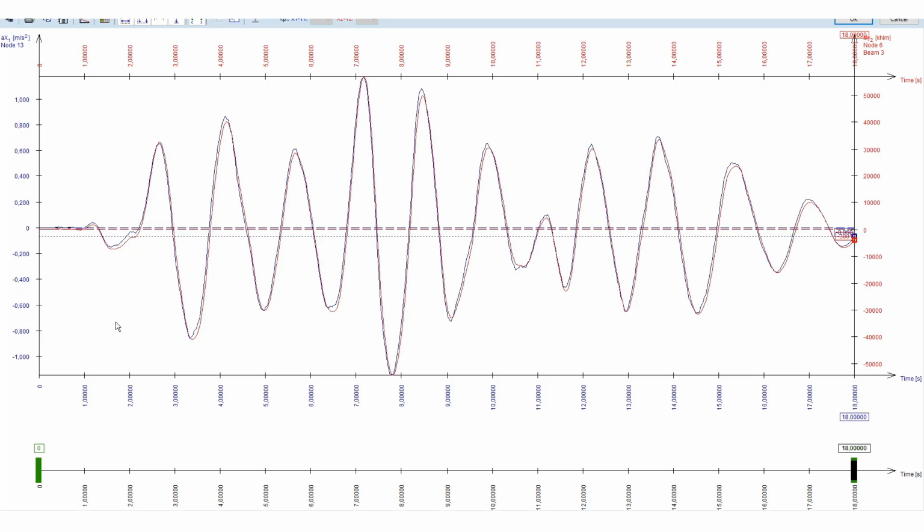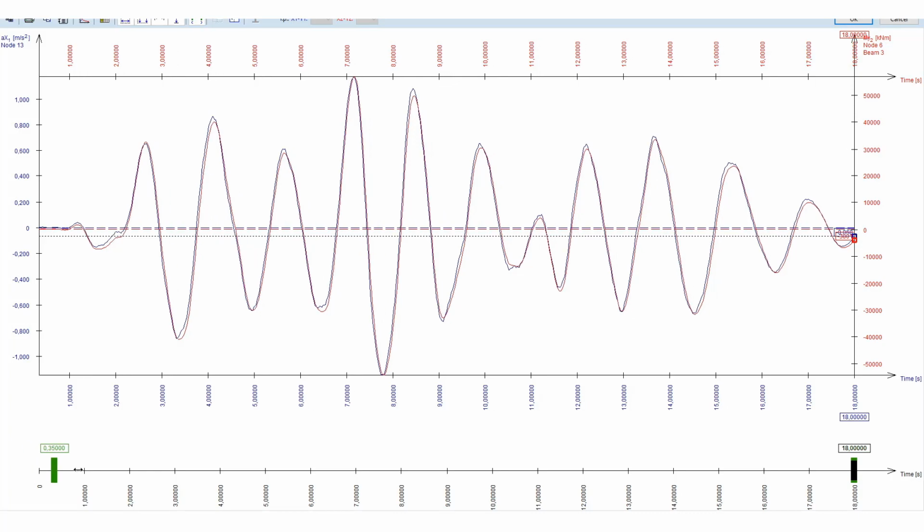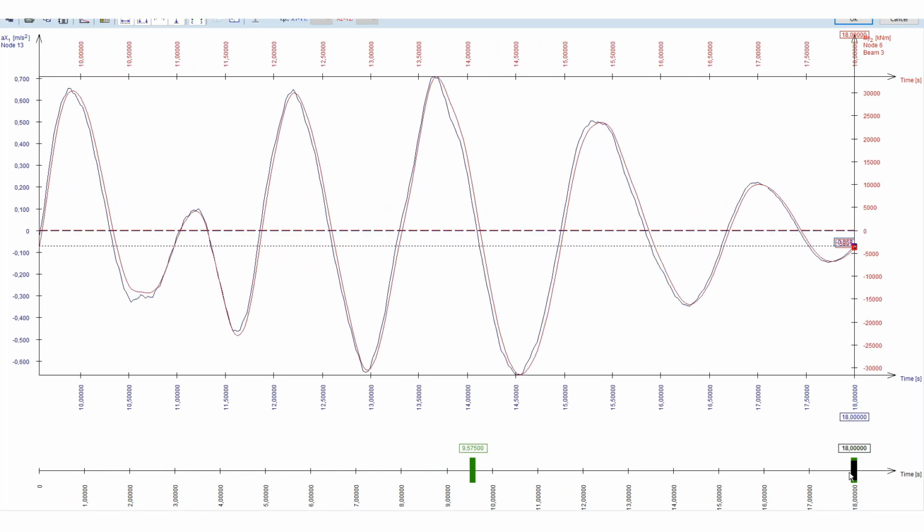Also, we can see the natural frequency of the deck pier system, described with a natural period of about 1.4 seconds. We can set same ranges on the axis, but only if the units are identical. We can also set the range of the plot to get a better and detailed view of the results.